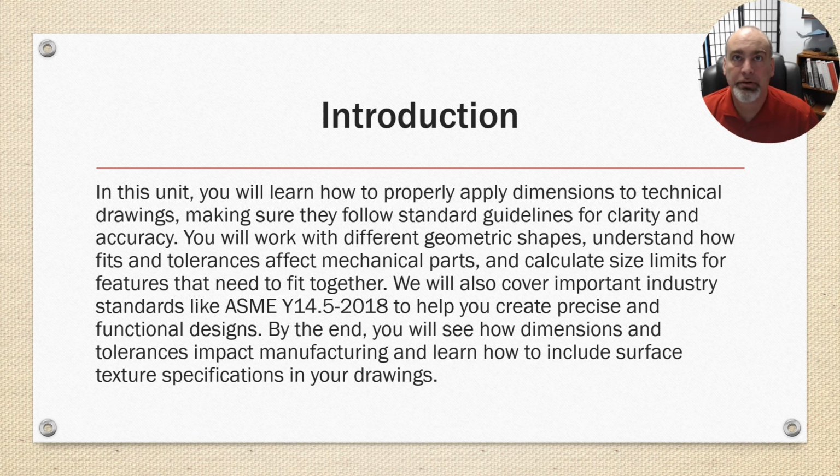Okay, in this unit you'll learn how to properly apply dimensions to technical drawings, making sure that they follow standard guidelines for clarity and accuracy. You will work with different geometric shapes, understand how fits and tolerances affect mechanical parts, and calculate size limits for features that need to fit together.